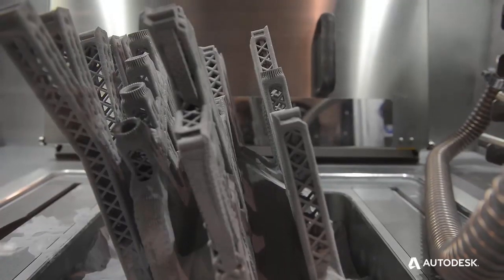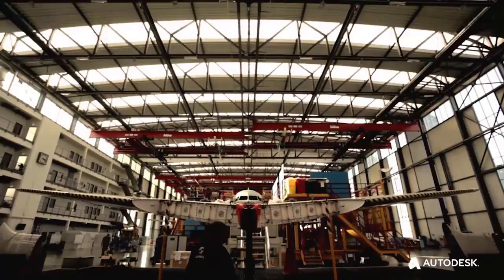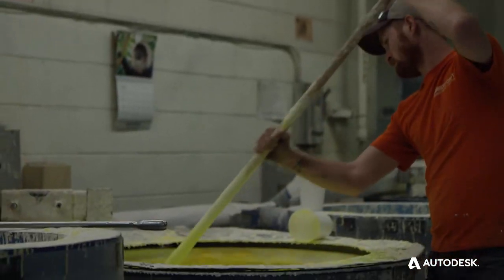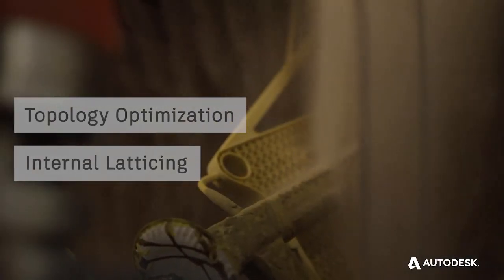The ability to create features that are exclusive to additive manufacturing in strong materials like stainless steel and aluminum broadens the horizons of what manufacturing can achieve and continues to accelerate the development of manufacturing design, software, and hardware. Perhaps the most exciting development in production manufacturing is the combination of additive and subtractive manufacturing, or hybrid manufacturing. Additive manufacturing has opened up the possibilities of what can be produced by removing many of the design challenges associated with subtractive manufacturing. In particular, lightweighting strategies like topology optimization and internal latticing are significantly more accessible using additive strategies.